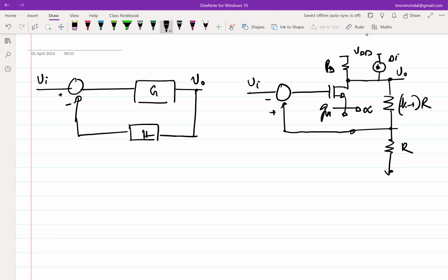Okay. So why do you think it will be the same? Okay, so there will be no current through the transistor. Okay, so why do you think there will be no current through the transistor? Okay, fine. So from the device perspective, he is saying this is an oxide, so no current should flow through the transistor. But when I say current flowing through the transistor, I don't mean current flowing into the gate, right? I mean current flowing between the drain and the source.